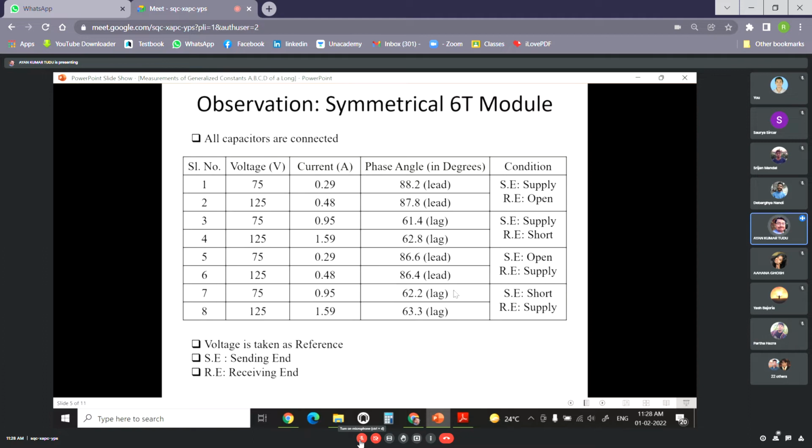While series reactors are used for limiting the fault current, shunt reactors are used for reactive power control. As I said, whenever we have a lightly loaded condition in the transmission line, shunt reactors are connected so that they absorb the reactive power from the system, so that the voltage goes down to its nominal value.